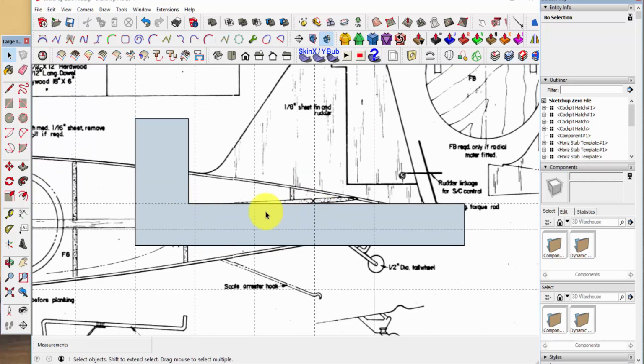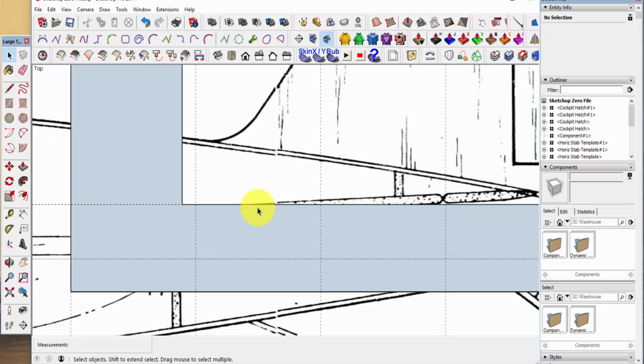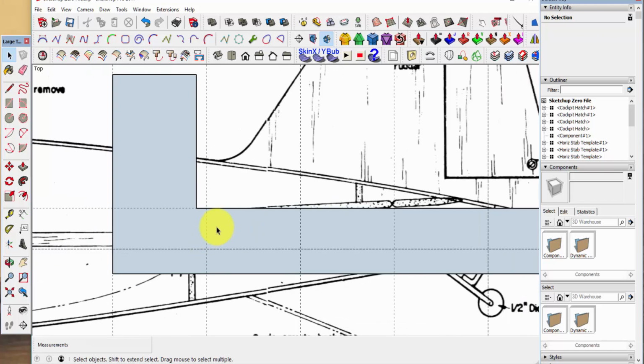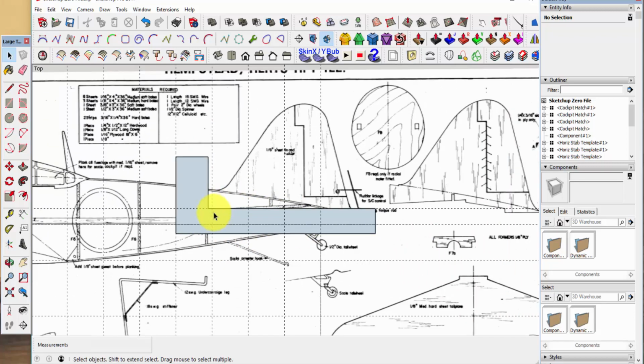Now one thing that I did not take into account, and that I probably should right here, is the thickness of that horizontal stab. So let's correct that, and that's going to be easy to do. I figure the thickness of that stab on a model aircraft of this size, covered with epoxy and fiberglass, 5 or 6 millimeters is plenty thick enough. So if we go with 6 millimeters, we can sand it actually to an airfoil shape.